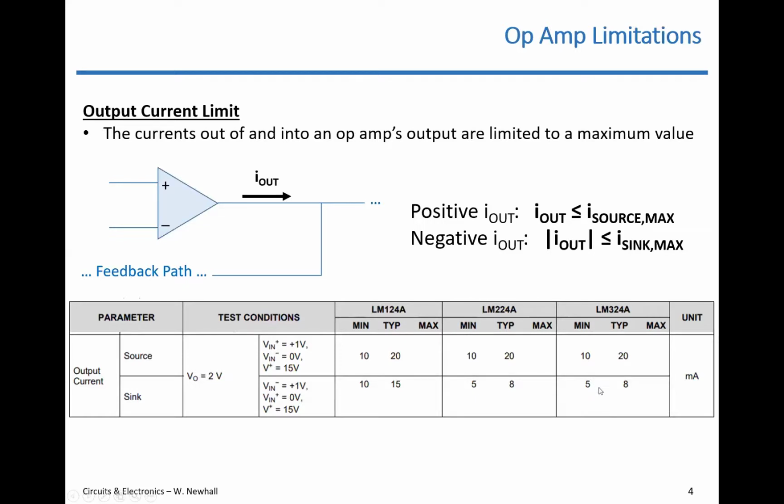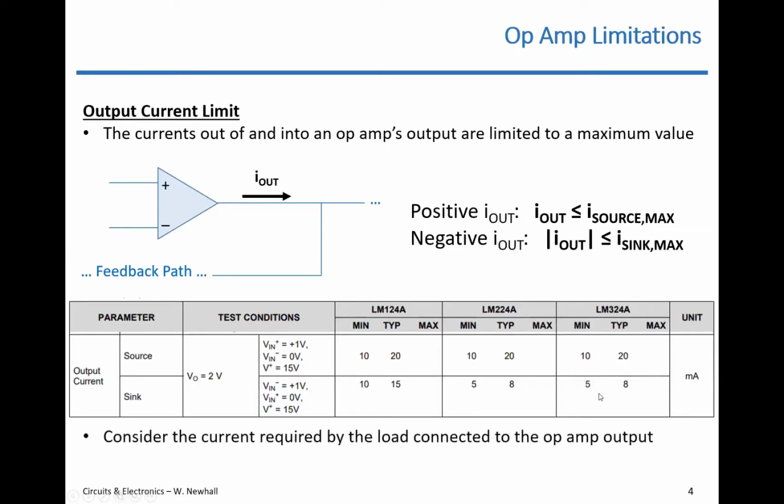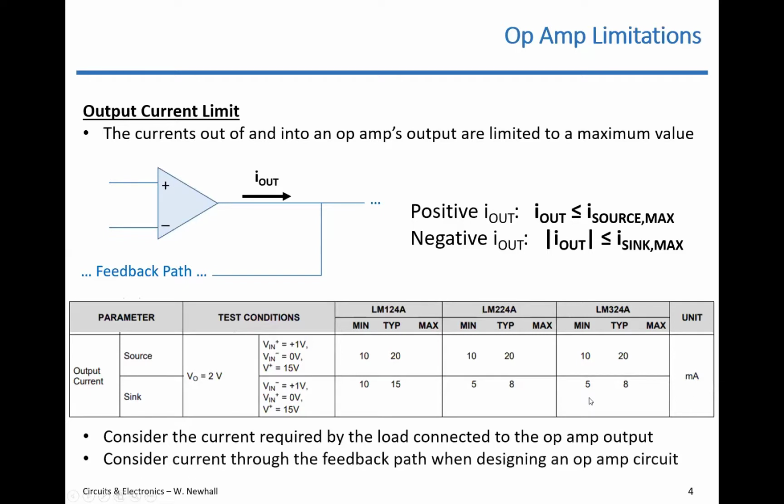So something to look at. Consider the current required by the load connected to the op amp, and also consider the current through the feedback path when you're designing a circuit. Okay, so some practical advice there that sometimes is left out of circuits class.